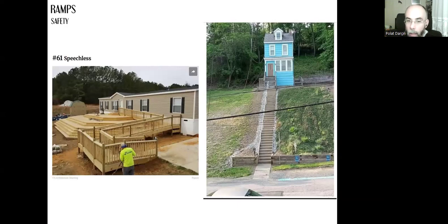problems. First elevating the entrance, creating all these steps, and then creating a very funny, idiotic, unnecessary ramp next to it is not a proper solution. We need to make good, accurate decisions about the grade level, the ground floor and the entrance based on the slope. We can change the slope, but it needs to be logical, not excavating the whole area thoroughly or filling the whole area to have a level surface.